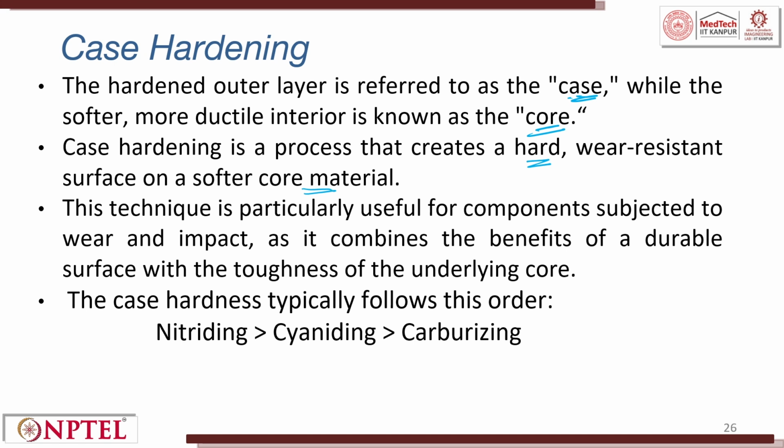This technique is particularly useful for components subjected to wear and impact, as it combines the benefit of a durable surface with the toughness of the underlying core. The case hardness typically follows the order nitriding, then cyaniding, then carburizing. Case hardening is extensively used in the automobile industry, toy industry, domestic industry, and many other places.